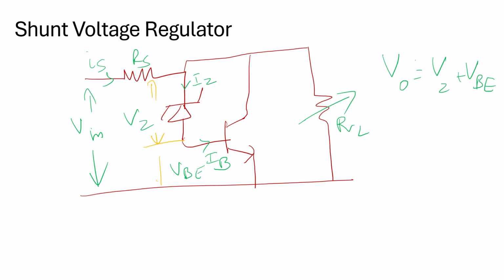So this is a shunt regulator circuit. The transistor shunt regulator circuit is formed by connecting a resistor in series with the input and a transistor whose base and collector are connected by a Zener diode that regulates, both in parallel with the load.